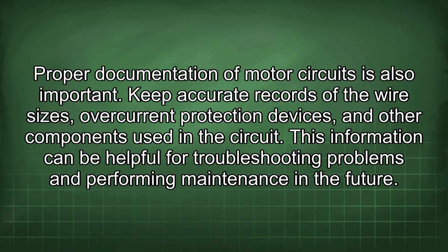Proper documentation of motor circuits is also important. Keep accurate records of the wire sizes, overcurrent protection devices, and other components used in the circuit. This information can be helpful for troubleshooting problems and performing maintenance in the future.